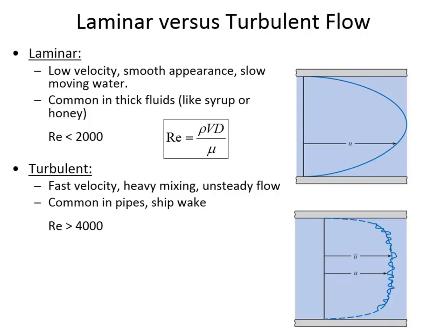The typical kinematic viscosity for water, if you don't have other temperature information, is 1 times 10 to the minus 6th meter squared per second. That's just a typical kinematic viscosity of water at about 20 degrees Celsius. So if you want to calculate the Reynolds number, you multiply the velocity times the diameter, then divide by 1 times 10 to the minus 6th, and you'll very quickly be able to have the Reynolds number.